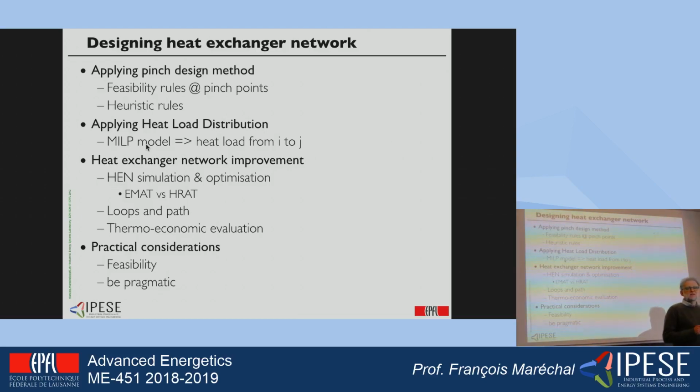needs to be optimized. So it means that the delta T minimum that is applied to each of the heat exchangers in the heat exchanger network design needs to be optimized, so that at the end we arrive at the best solutions when we do a thermoeconomic evaluation.